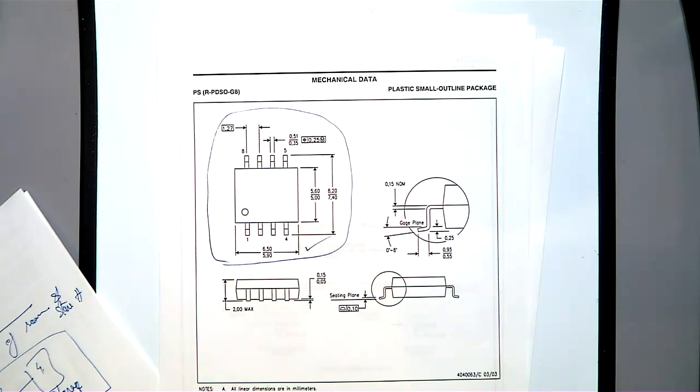The answer to your question is that IC manufacturers follow some guidelines, and accepted footprints are there. The modification you may have to make is, for example, an SOIC with a small modification, maybe you are using a guard ring, something like that. I'll tell you what a guard ring is. Then you may have to do a modification. Otherwise, it will be standard. So that is all about the footprint.